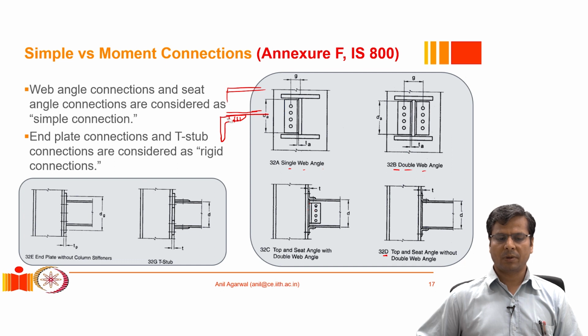Also, in order for it to be able to resist that moment, we may use more than one row, at least 2 rows or more than 2 rows of bolts if we are going to use bolts, or a deep connection, a long weld, so that it can effectively resist that moment, that eccentric moment because of the eccentricity of the load. The effective load is acting here, whereas the connection is actually here, so there is an eccentricity that needs to be resisted effectively.